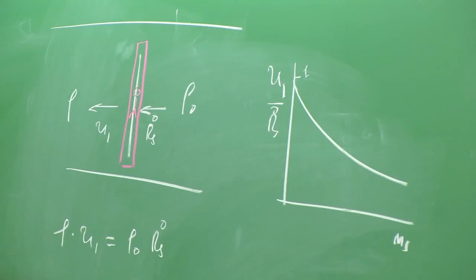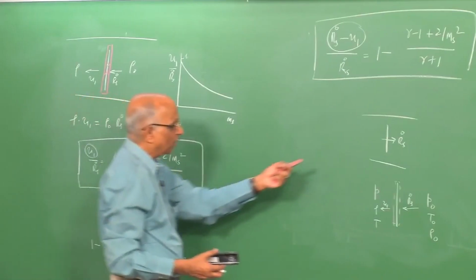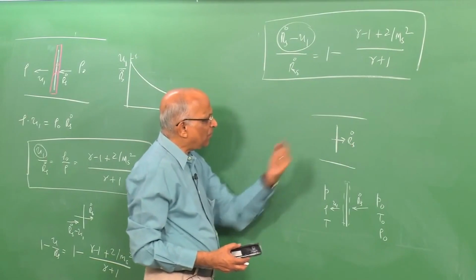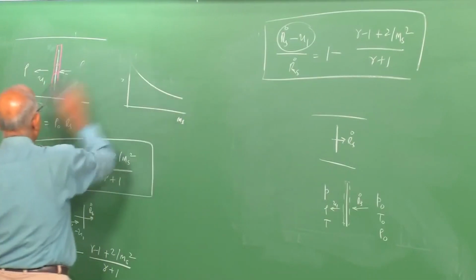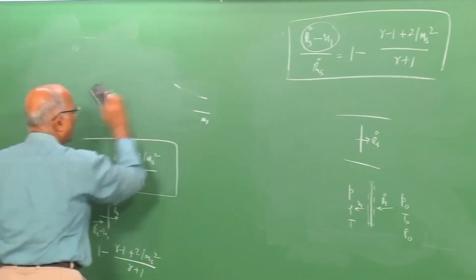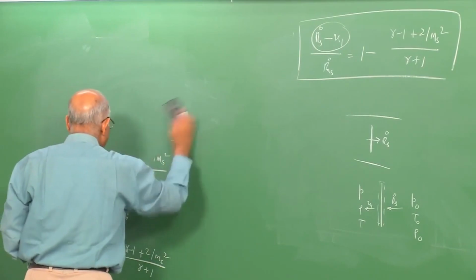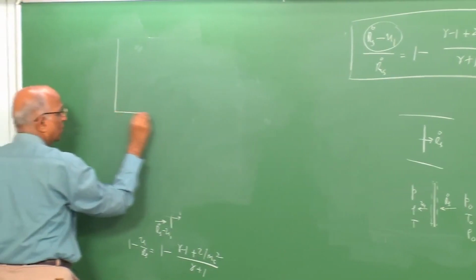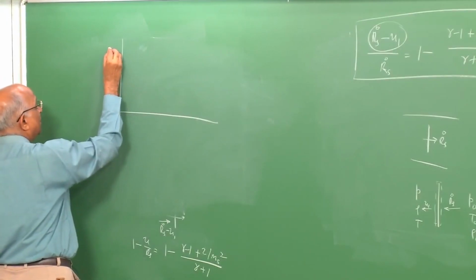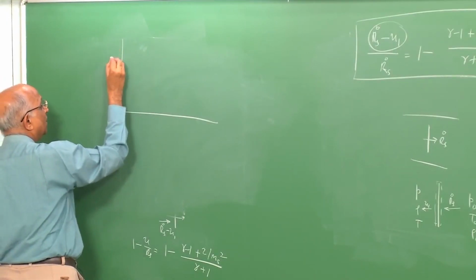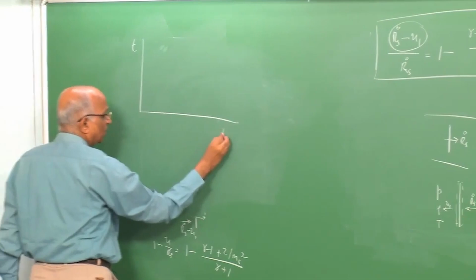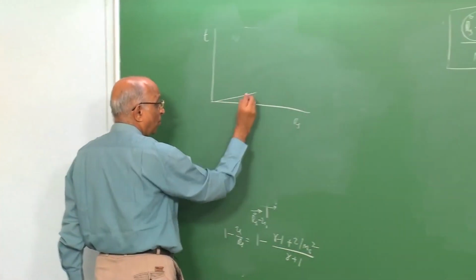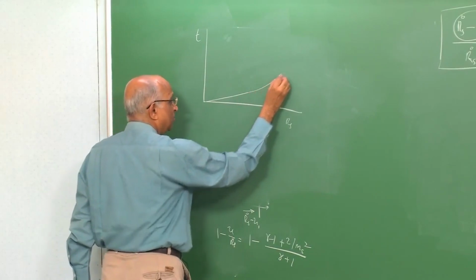Well, this is all about the shock relationships for the case of a constant velocity shock, but the problem we are interested in is something different. We have the blast wave which is not a constant velocity wave, and that is where we got started today. We are interested in something like, let us say in the streak diagram T versus Rs, we start with a strong shock wave travelling at high velocity and keeps decreasing.